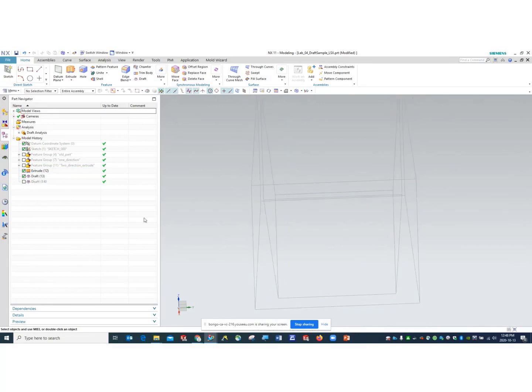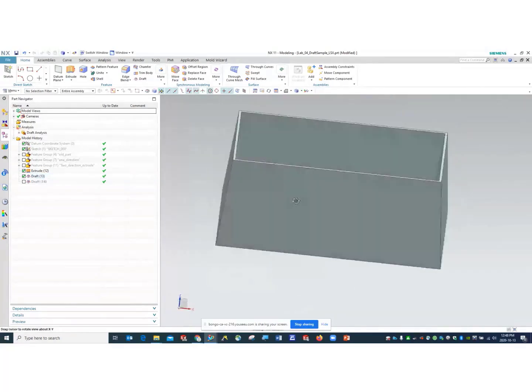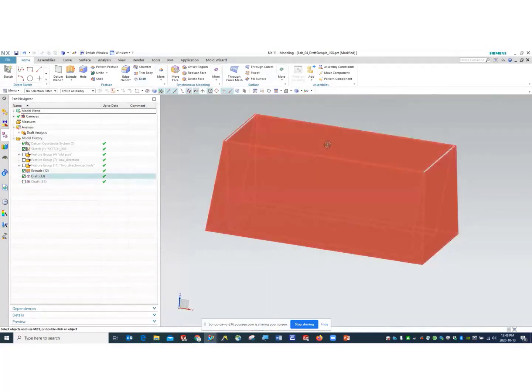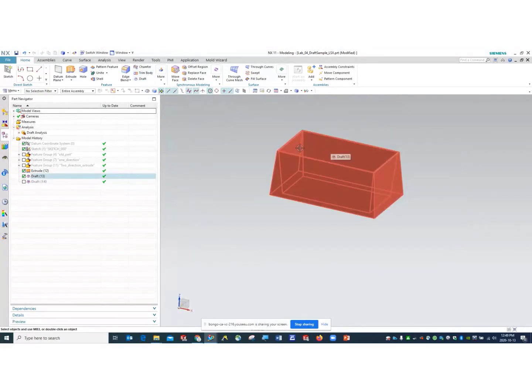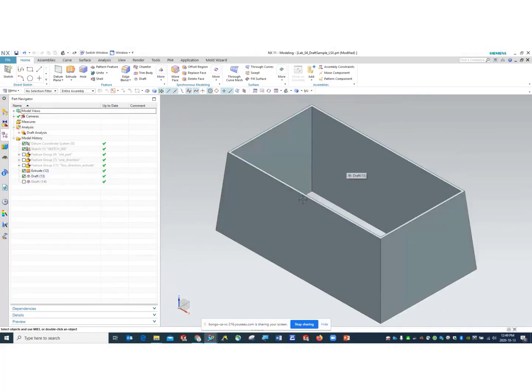When you are going to design a mold and the draw direction, the draft angle is measured differently for inner dimension and outer dimension. Inner wall and outer wall will be different, so pay attention to that. This is a wall. You can create the draft command